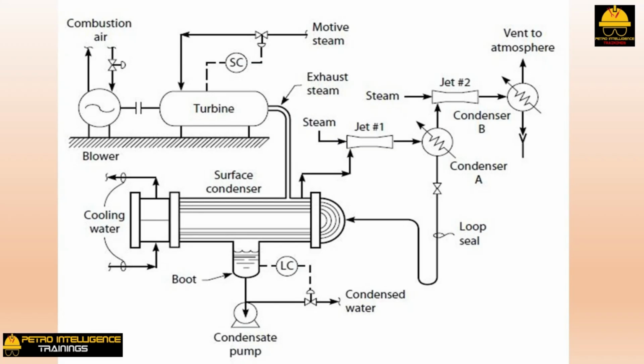Function of the final condenser. We discussed before that the drain from the final condenser shown in picture had plugged. Rather than unplugging the drain, could we have simply disconnected the final condenser, condenser B, and vented the discharge from the secondary jet, jet 2, to the atmosphere? Would this have helped or hurt the vacuum in the surface condenser?